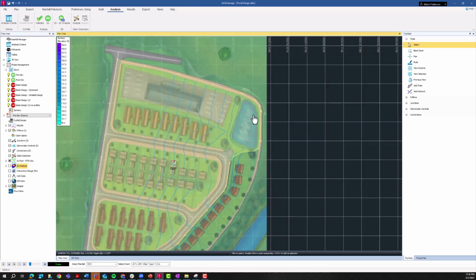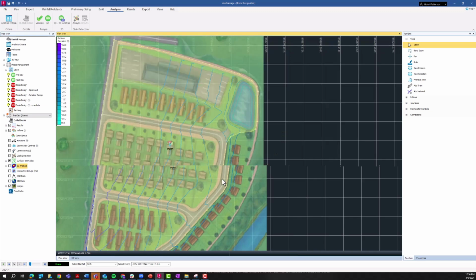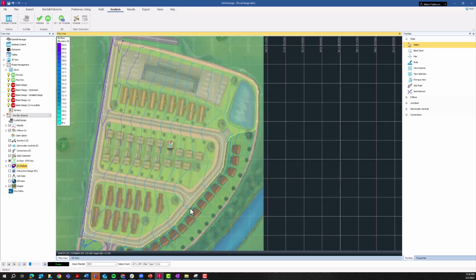So typically when you're adding a pond, the purpose is again to store that water, store the runoff, the increased runoff that we see from our site due to the increased imperviousness values, and detain that and slowly release it so that it's not all just draining off the site. We're going to be sizing this pond for a water quality event. So again, all of this just depends on the jurisdiction that you're working in, what those requirements are going to be.